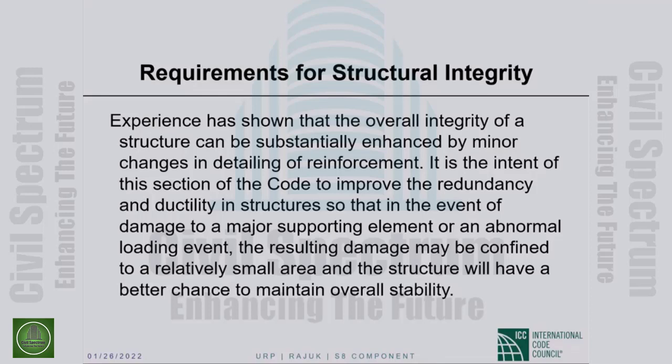I don't know what that means, but the dowels would have to be lapped with the upper bars and the lower column bars, right? The lap splice length we talked about, even yesterday there was an example. You are lapping column bars, so you will have to provide a class A or a class B splice.